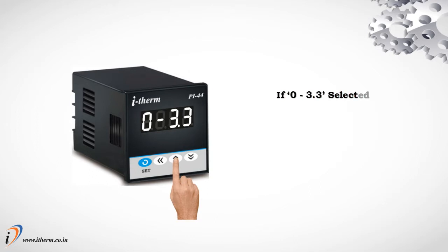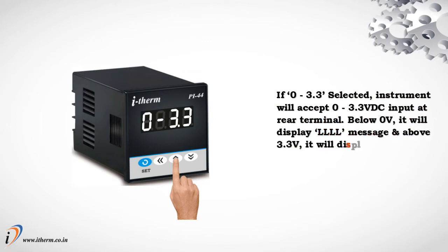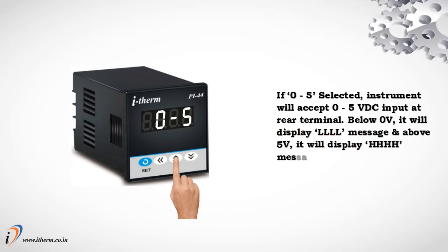If 0 to 3.3 selected, instrument will accept 0 to 3.3 volt DC input at rear terminal. Below 0 volt, it will display L message, and above 3.3 volt, it will display H message. If 0 to 5 selected, instrument will accept 0 to 5 volt DC input at rear terminal. Below 0 volt, it will display L message, and above 5 volt, it will display H message.